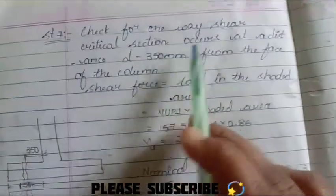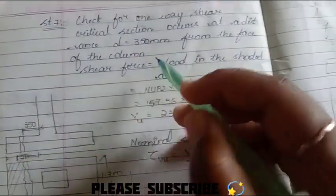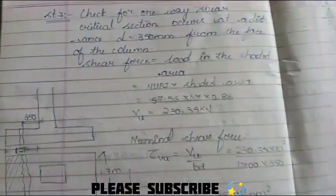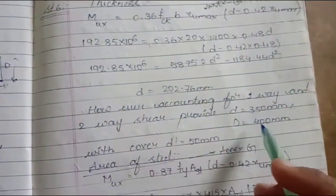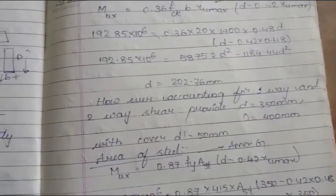Here we are having the check for one way shear. The critical section occurs at a distance of d from the face of the column. I've already told you, we know the small d, the effective depth value. Considering the effective cover, we have just taken this 350 mm. Using this formula we have calculated the small d and capital D, the effective depth and the overall depth. So for this effective depth we are analyzing this.